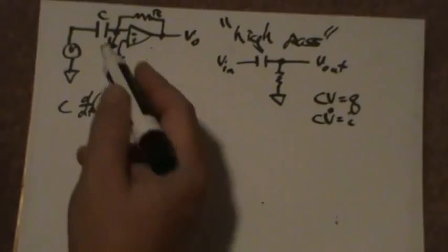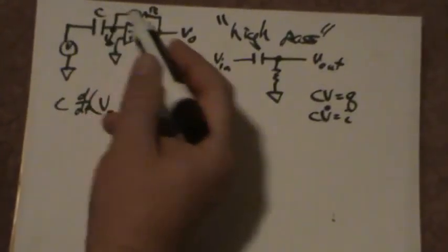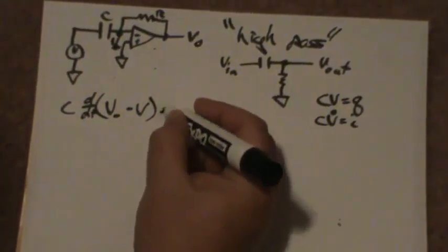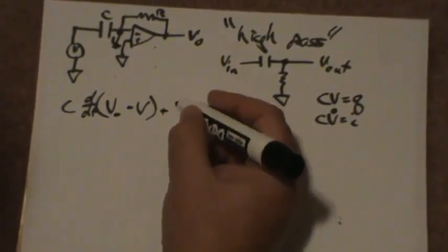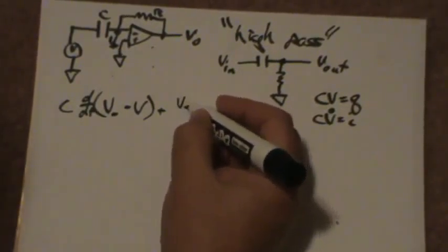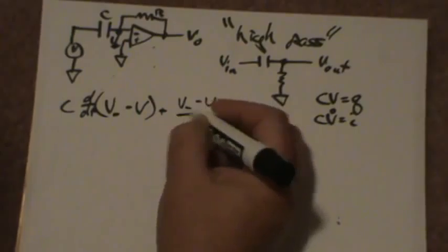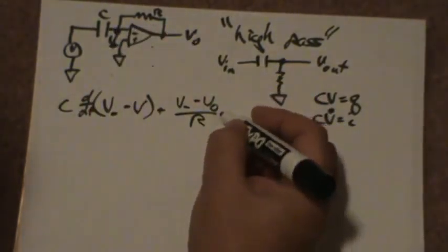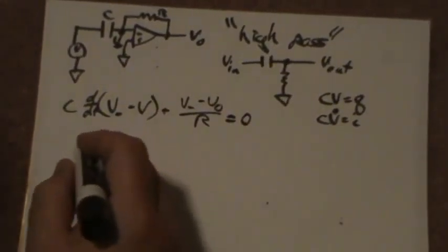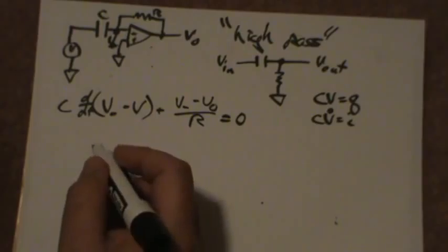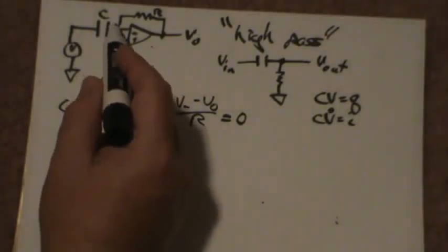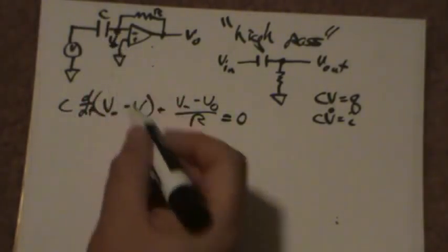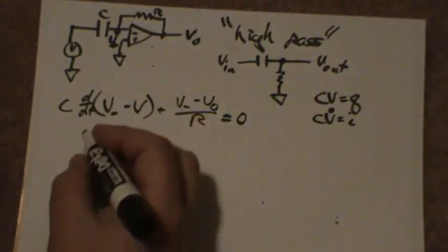So this is the current that's flowing through here. I get the current through here. That one is just basic Ohm's law stuff. So I get (V minus minus V out) all over R. That's got to be equal to the current that's flowing into here, but we assume that's 0 for an ideal op amp. It should be pretty darn close to 0 anyway. Now V minus has to equal V plus, and V plus is grounded, so those go to 0.